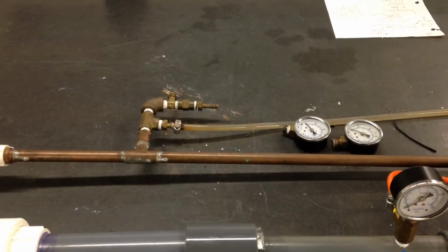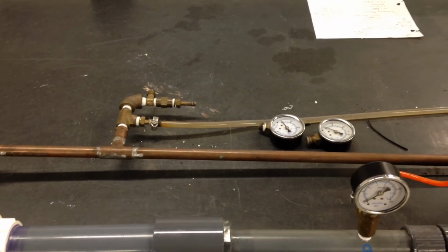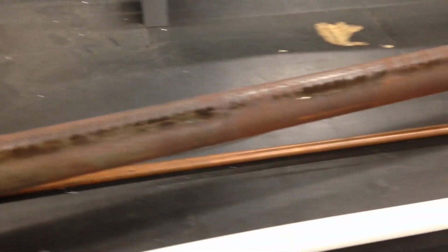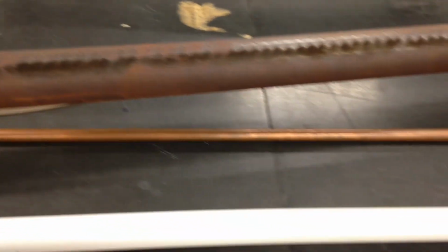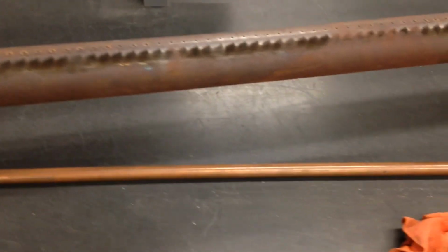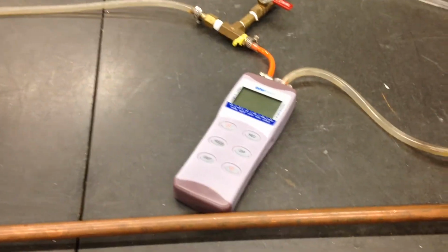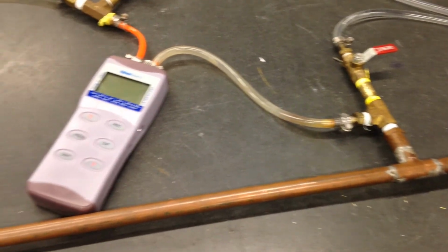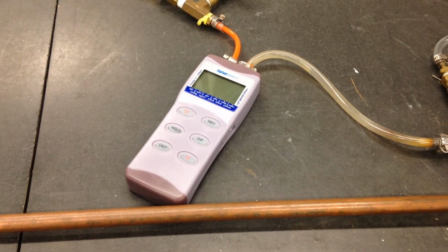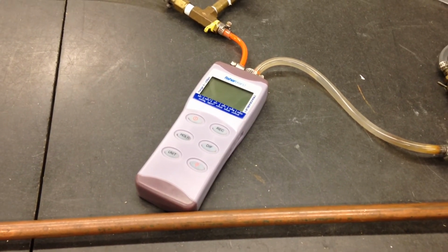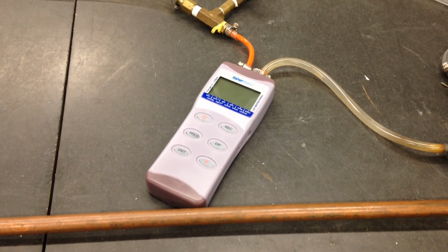It's a little hard to see in places, but here is the beginning, the copper tubing, and we'll just go right past where it goes behind the rotometer. And this copper tubing, the length is given in the procedure, and the diameter and all the dimensions that you'll need. And the head loss between the port you saw just moments ago and this one right here is measured by this digital flow meter. And we'll be able to do a Moody Chart correlation based upon that.